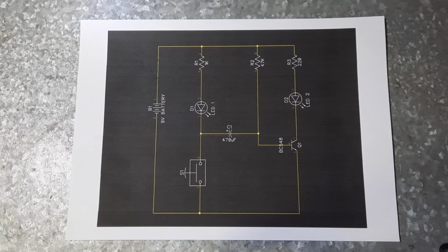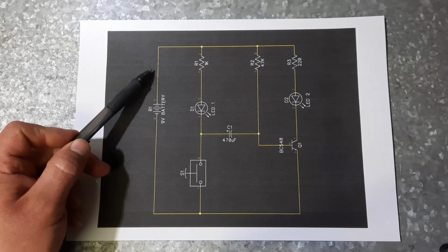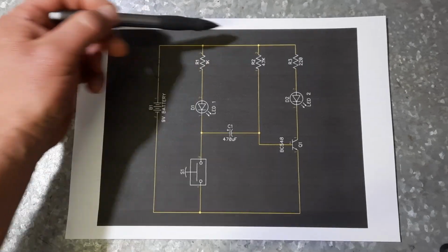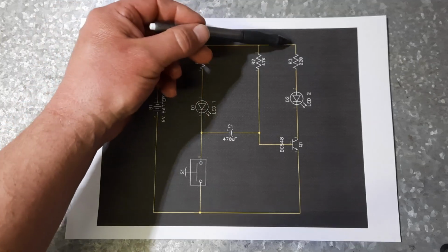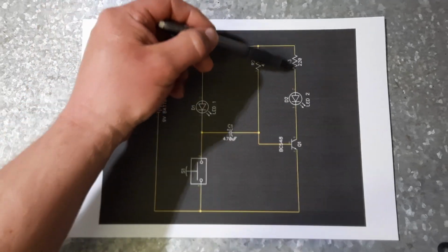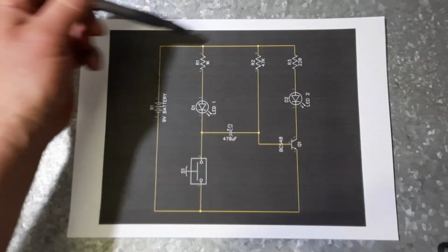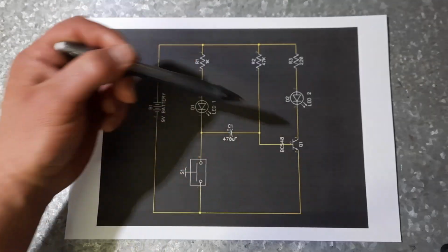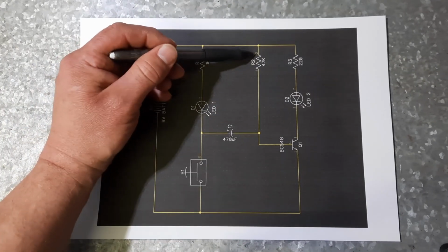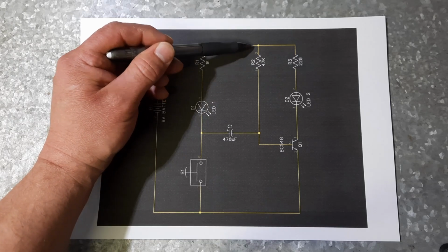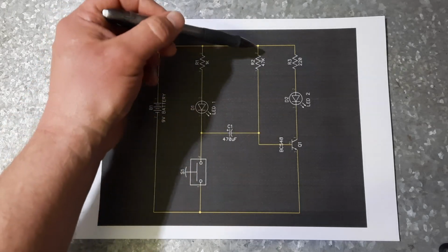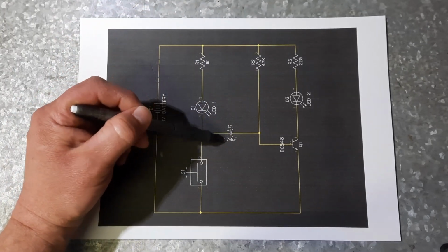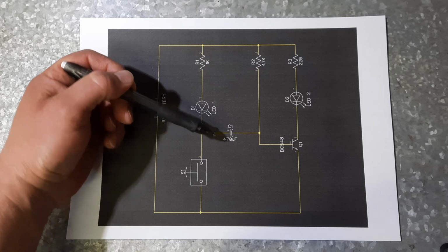So when we first power this circuit up, a few things are going to happen. When we first turn this switch on, as discussed, power is going to flow from here down to here, saturate our transistor. It's also when that turns on, power is then going to flow through here as well. So simultaneously, we have power flowing down here and through there. This resistor here serves 2 purposes. Not only does it serve a purpose of limiting the current through the base of the transistor, it also is going to affect how this capacitor charges and discharges.